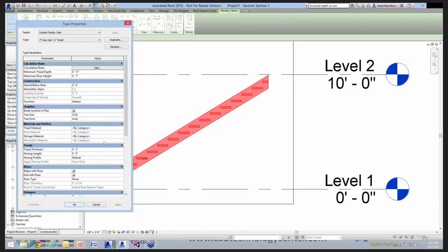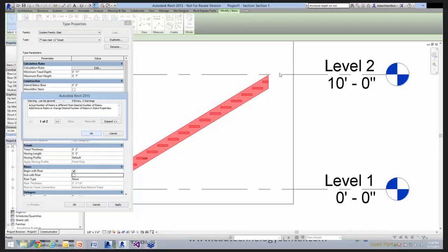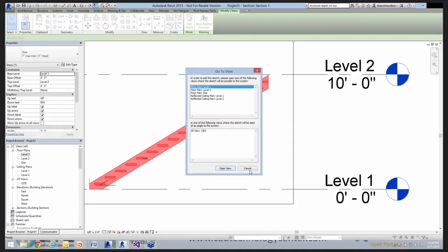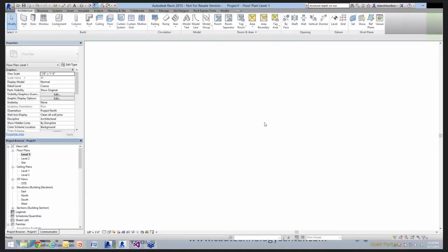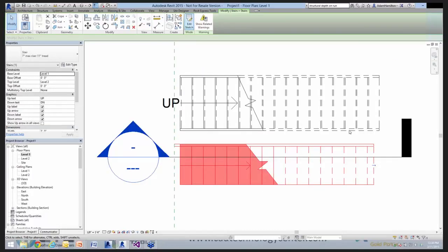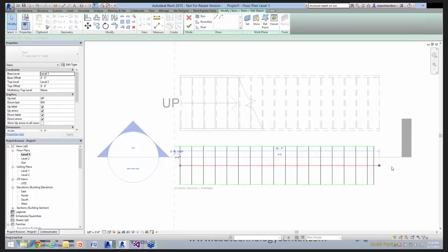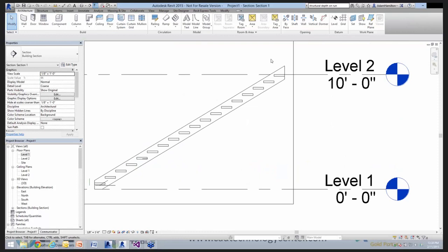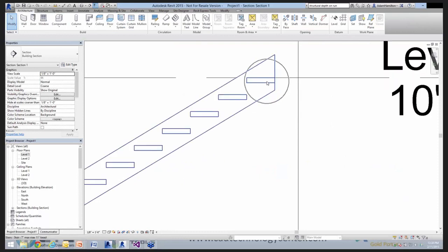Here you'll see end with riser, because you'll be able to see it over here. To end with a riser, you hit apply, and it redoes the math for you. You will need to modify your sketch, but you're able to add that additional tread up, and now you can end with the tread versus ending with a riser.